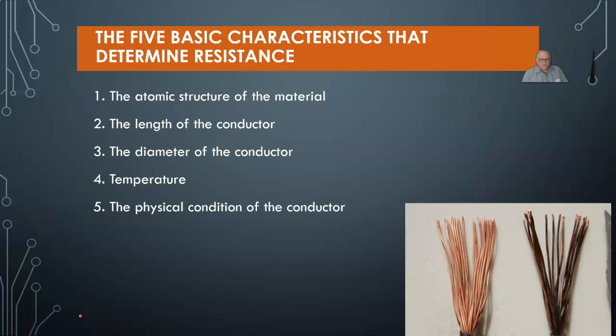Now, those first four, that's what the engineers are looking at when they're deciding what size wire they need to use on this particular circuit. Based on if it's under the hood, it's going to be hotter, so it may need a little bit larger wire than if it's under the dash. How many amps are going to flow through it? How long is it? That's what they're going to use to figure out what size wire they need.